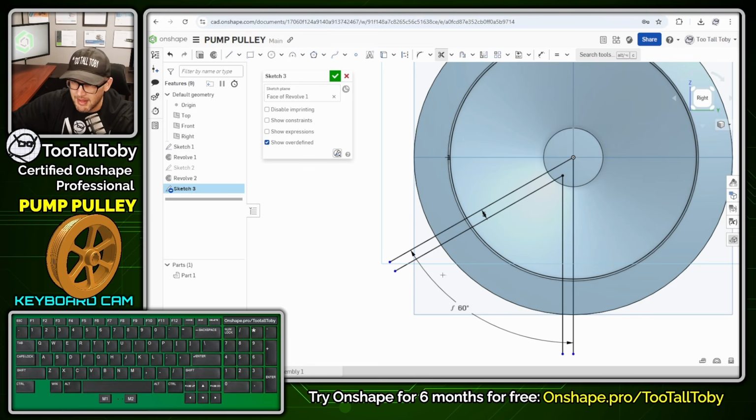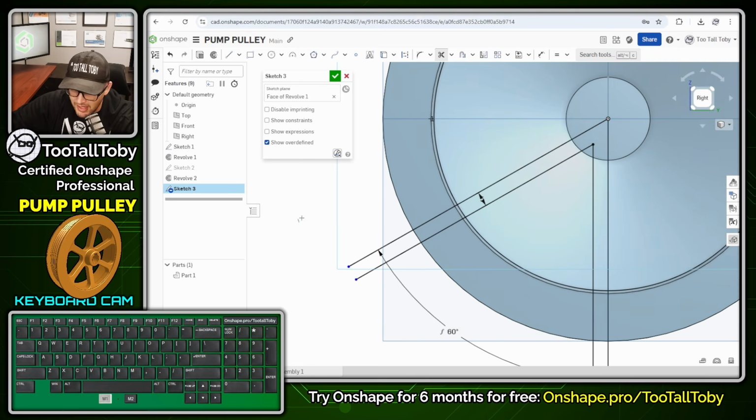And the way the trim command works is when you left click and drag, you make this little squiggly. Well, what you do is you left click and drag through some other sketch geometry. So I can left click and drag through that offset arc, and I can left click and drag through that offset line, and I can left click and drag through that offset arc. And that leaves me with this nice triangular wedge here in the middle.